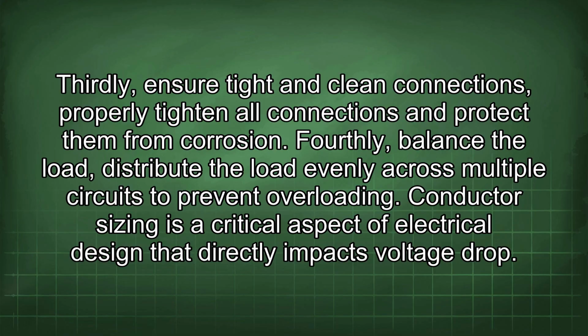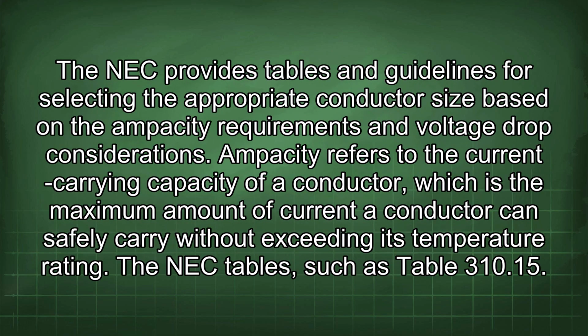Conductor sizing is a critical aspect of electrical design that directly impacts voltage drop. The NEC provides tables and guidelines for selecting the appropriate conductor size based on the ampacity requirements and voltage drop considerations. Ampacity refers to the current carrying capacity of a conductor, which is the maximum amount of current a conductor can safely carry without exceeding its temperature rating.